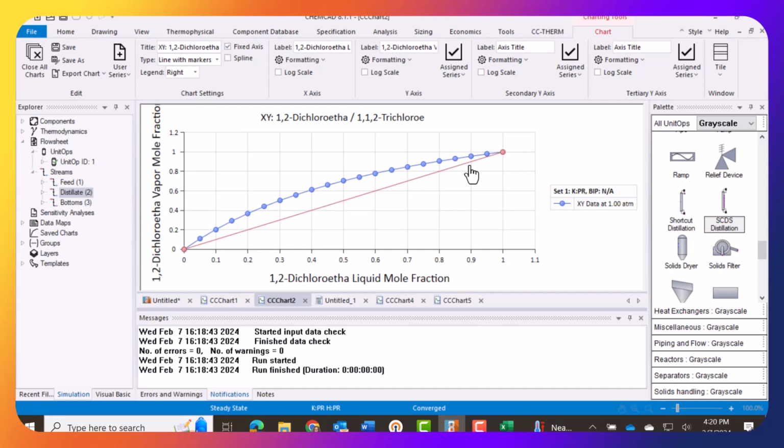Now, what we're going to be doing next is we're going to start looking at multi-component systems. I'm not going to be able to do those using the simple McCabe-Thiele as a starting guess. So the first thing we'll have to do is come up with the estimate that's going to be our starting guess. When we get into our simulation, that's going to be our shortcut distillation. But then I have to ultimately do the rigorous combined mass and energy balances.